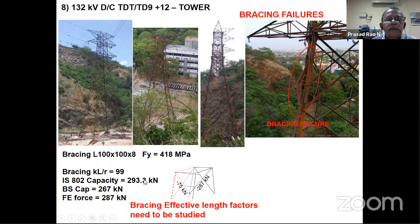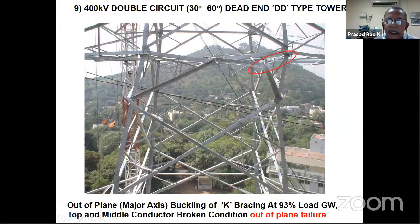It's another bracing failure, a typical out of plane buckling. This is because of insufficient secondary bracing. The secondary bracing member force is more than 2.5. Because of that, this bracing failure is an expected failure only. It has to fail in x only, but because of the secondary bracing, it has happened.